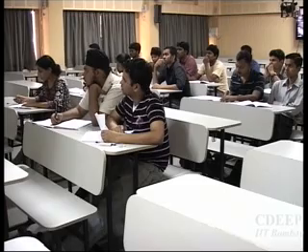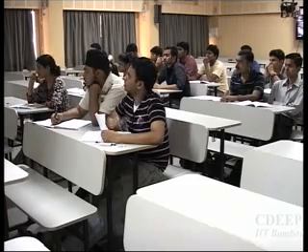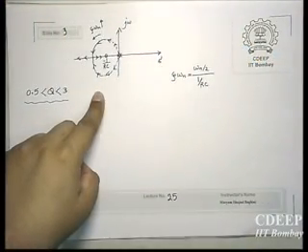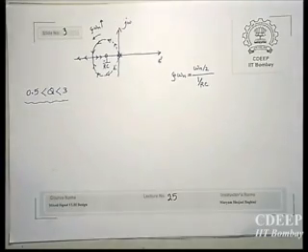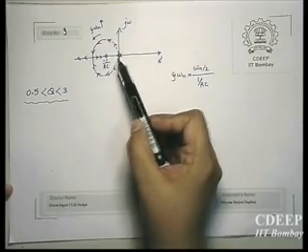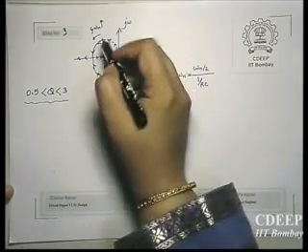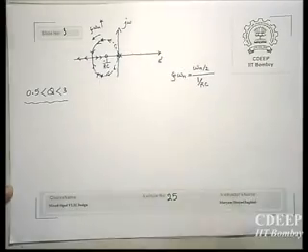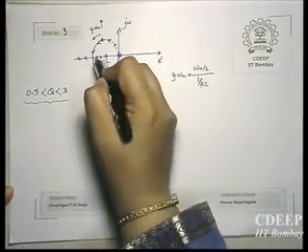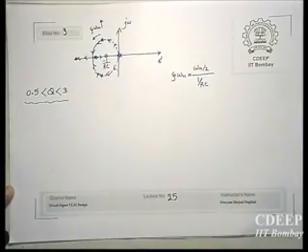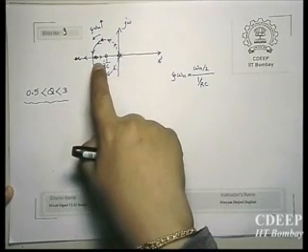Time constant eventually is, see, these arrows show poles, right? For example, suppose if your zeta is 0, eventually you are here, right? When R is 0. Now when you move somewhere else, for example, you are here, these are your poles. Suppose you are reaching the real axis. So your dominant pole now is the value which is closer to 0.